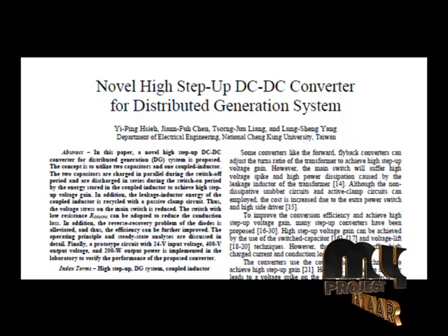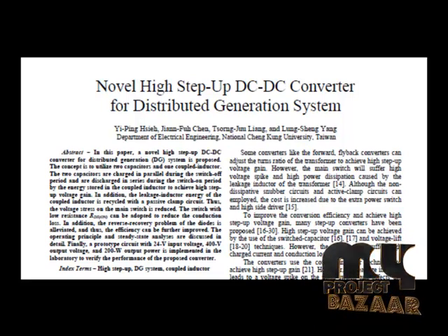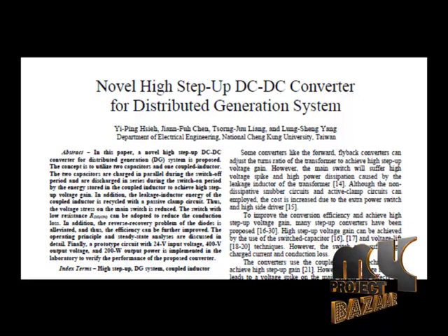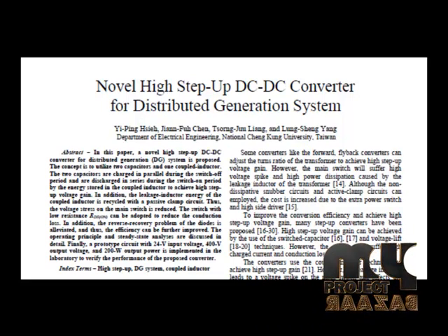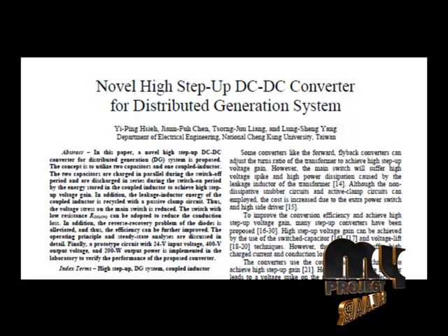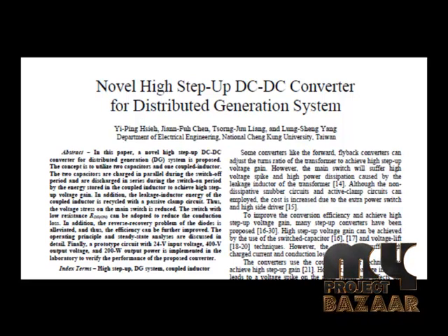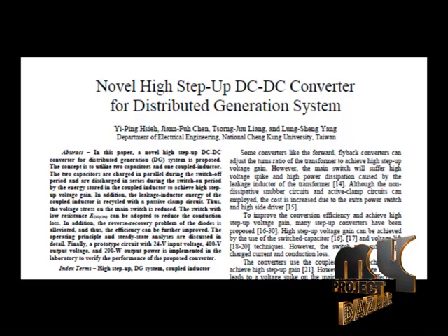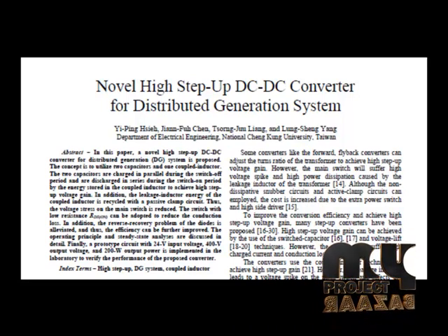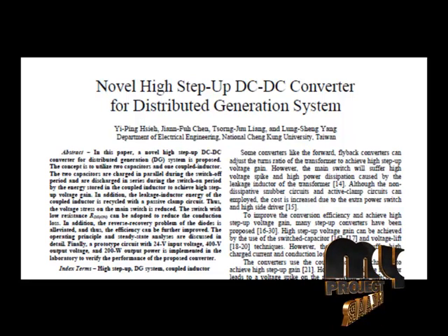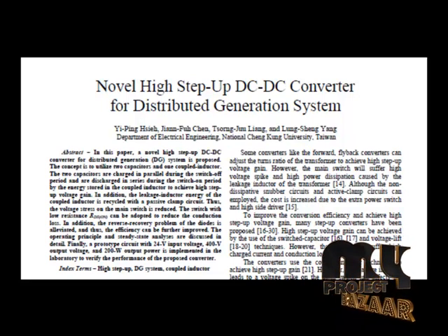Switched DC to DC converters offer a method to increase voltage from a partially lowered battery voltage, thereby saving space instead of using multiple batteries to accomplish the same thing. Most DC-DC converters also regulate the output voltage. Some examples of extensions include high-efficiency LED power sources, which are a kind of DC-DC converter that regulates the current through the LEDs, and simple charge pumps, which double or triple the output voltage.